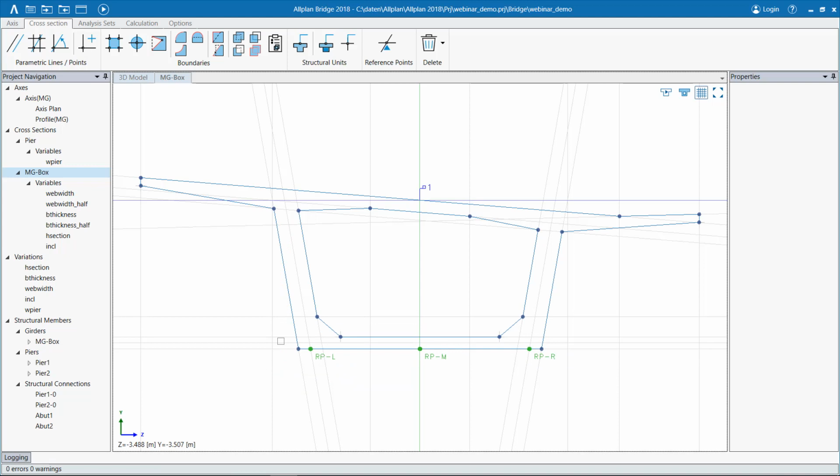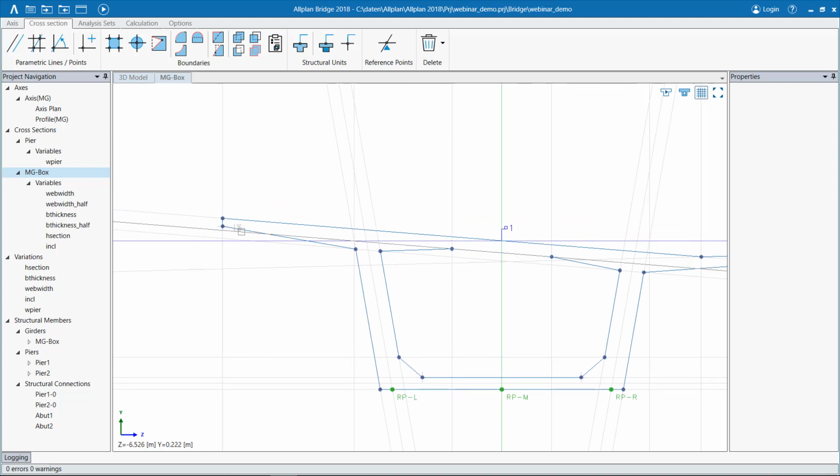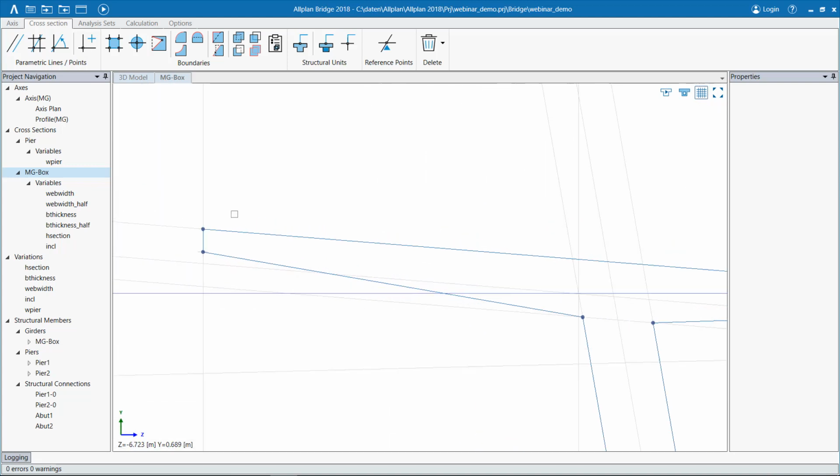So if I would use parametric points, I would need to define this dependency for each point particularly. However, for other cases, like here where there is no variation, I can as well use a parametric point, like here for this bottom position of the cantilever. And then it's maybe in some cases more quick than generating two lines.